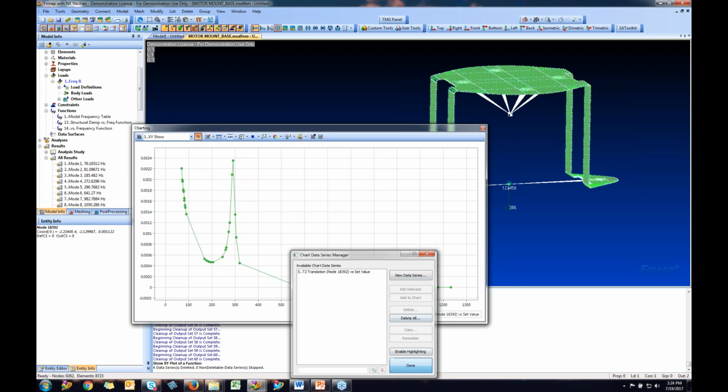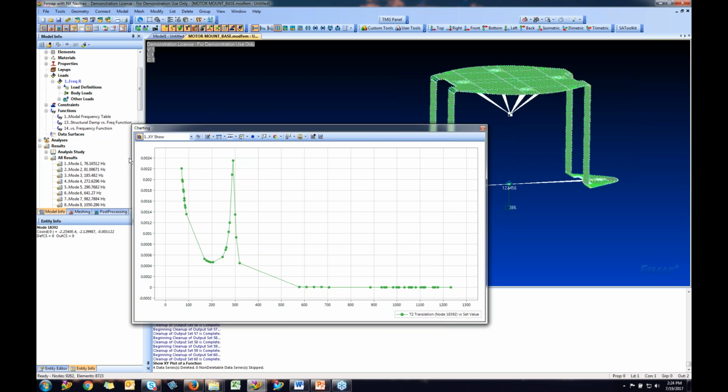So now I can visually see what went on. Now, these values appear to be extremely small. My structure is a little too stiff here, made it out of steel. But this value is 20 times higher, 20 times magnification of my static run. So it's at these frequencies that it is being excited 20 times my static run. So we are seeing this large increase in dynamic loading.